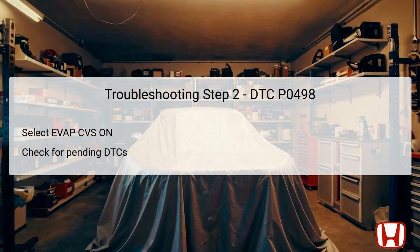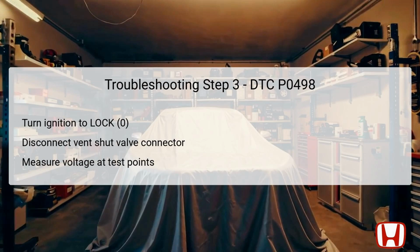Step 3 focuses on checking the integrity of the wiring related to the EVAP canister vent shut valve. Start by turning the ignition switch to the LOCK 0 position to ensure the vehicle's electrical systems are safely powered off. Next, disconnect the 2P connector associated with the vent shut valve. This is crucial because it isolates the valve for accurate testing. Now, turn the ignition switch back to the ON II position. Measure the voltage across test points 1 and 2 of the vent shut valve connector.